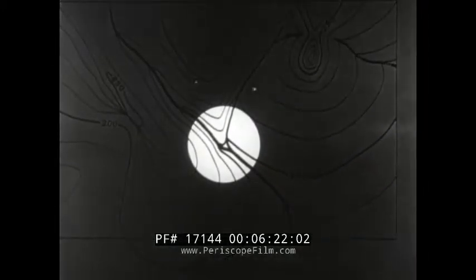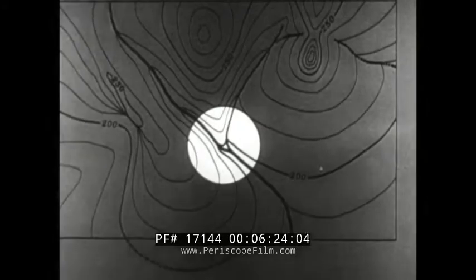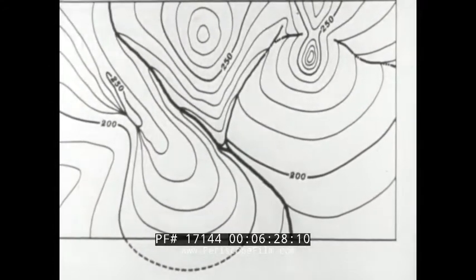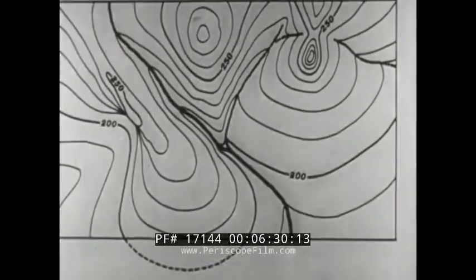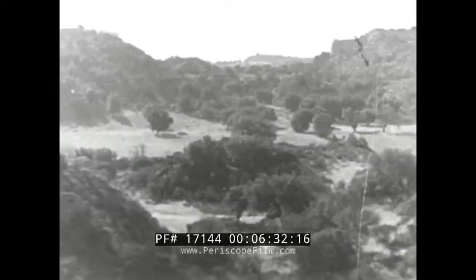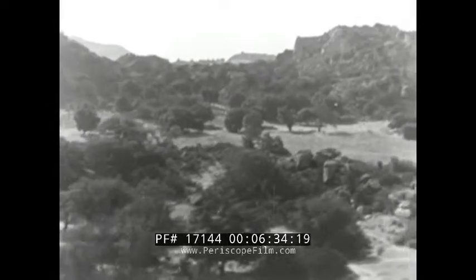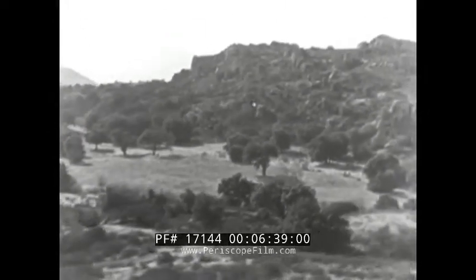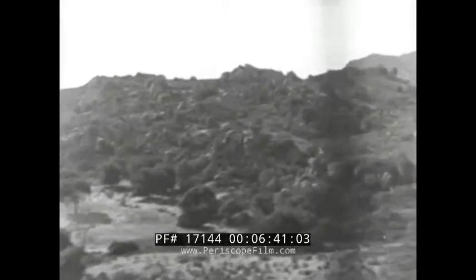Observe the characteristic appearance of the contours at a stream junction. On a water-worn terrain such as this map represents, adjacent contours resemble each other. This simply means that the change in slope and in the form of the ground are gradual.